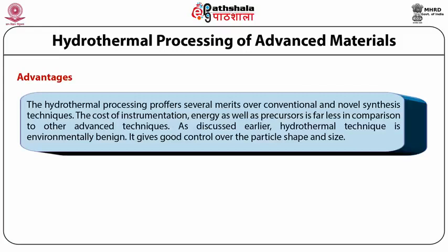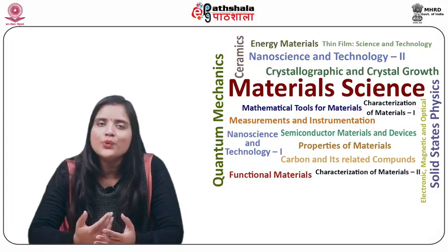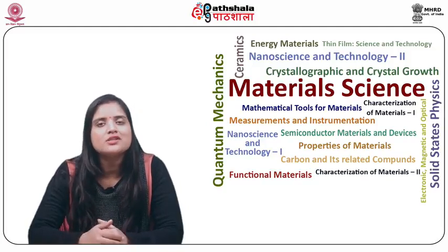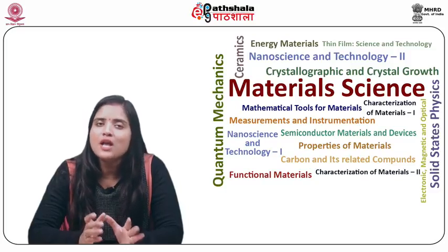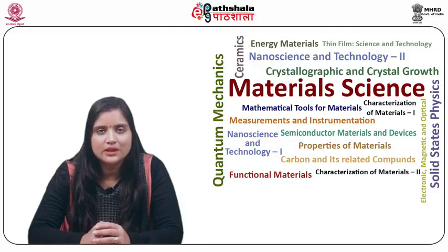The cost of instrumentation, energy, as well as precursors is far less in comparison to other advanced techniques. As discussed earlier, the hydrothermal technique is environmentally benign. It gives good control over the particle shape and the size. Another advantage of using the hydrothermal method over other techniques for crystal growth is that crystalline phases which are unstable at the melting points can also be grown with this technique.